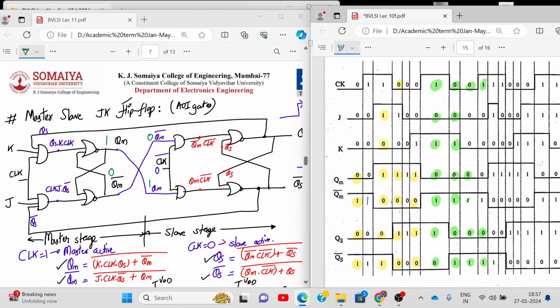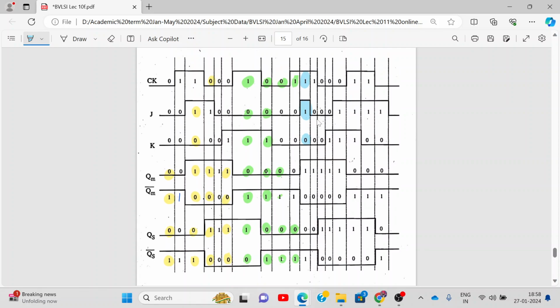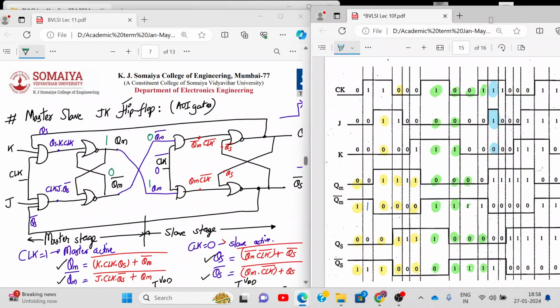अभी ये प्रॉब्लम आ गया, इधर एक ग्लिच आ गया, लेट्स से, राइट? ये स्टेट देखो अभी, clock is 1, J is, let's say for some other reason J 1 हो गया and K 0 हो गया for some reason. Now what will happen? What should happen? This should be 1 na. J is 1, K is 0 means it should be 1 0, right? Yes, sir. So master का output changes from 0 1 to 1 0, and the slave will remain same because it's off na.